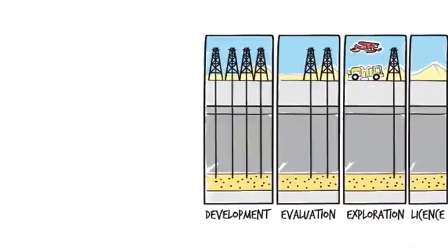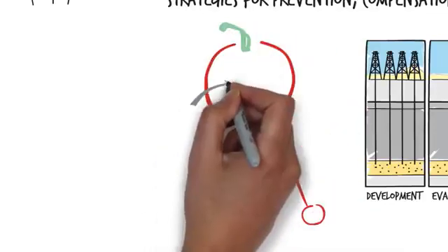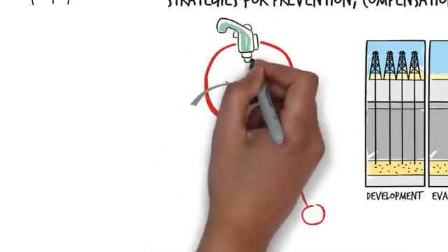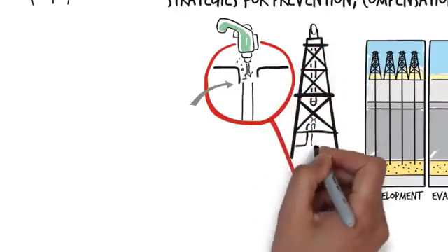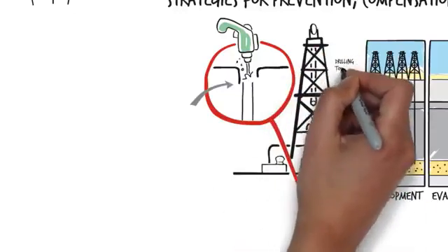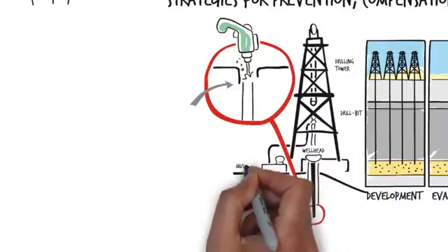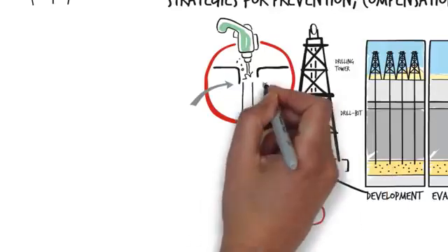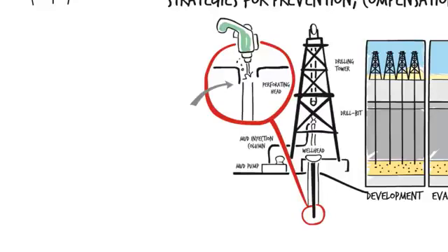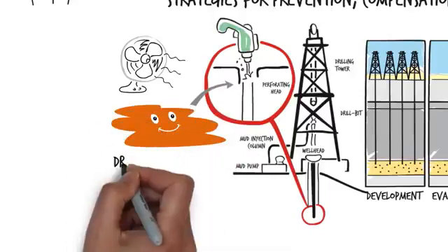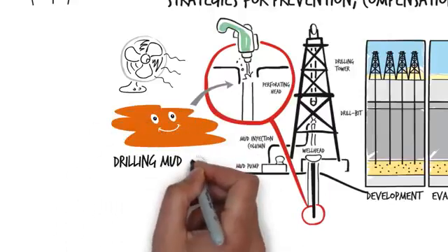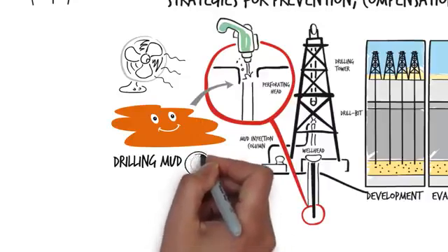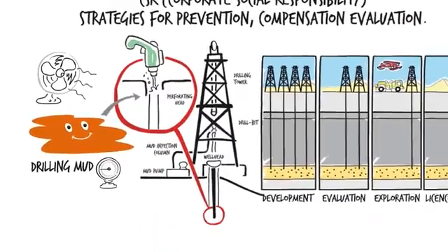let's start drilling. For this purpose, we use a perforating head, which consists of a drill bit connected to the surface, with a drill string formed by threaded steel pipes. During the drilling process, more sections are screwed on as the well gets deeper. The perforating head is kept cool and clean with a fluid called drilling mud. A valve system controls pressure, and there's a security system which prevents uncontrolled flows reaching the surface.